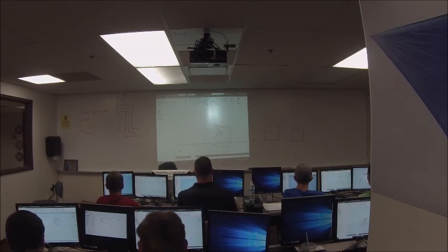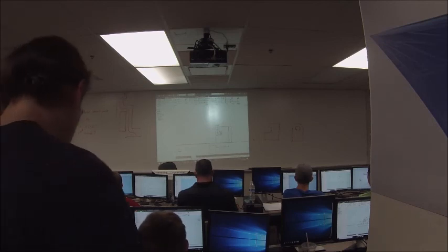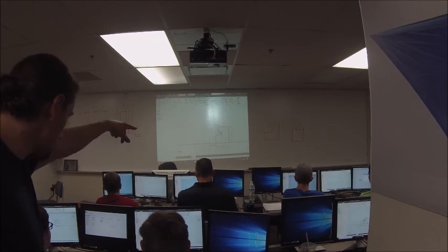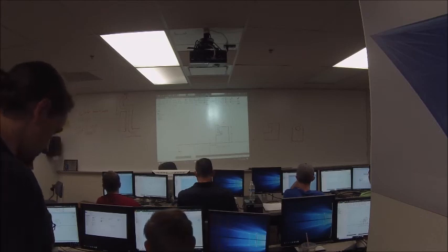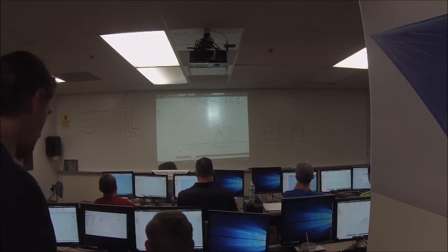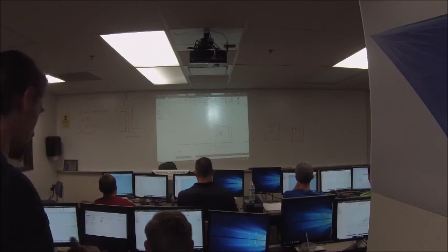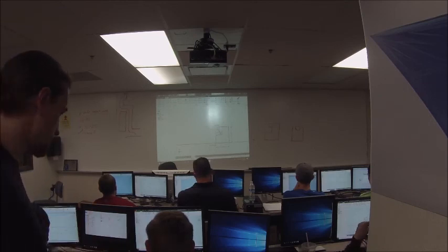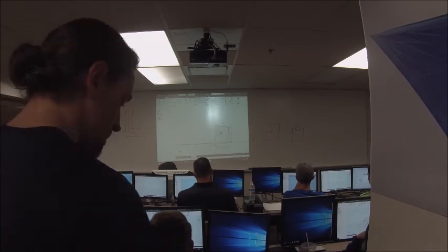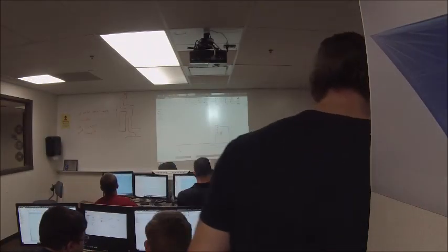Austin, looks like you need to place a few more dimensions there. So you need to just look on my screen. You see how I have a bunch of dimensions up there? Just go ahead and do the same thing. Click one line, click the other. There. Yep. And then say how big you want it to be. And just go through and specify the size of each thing so it's locked in place. And Tyson, you want to help him do what you just did when he's done.